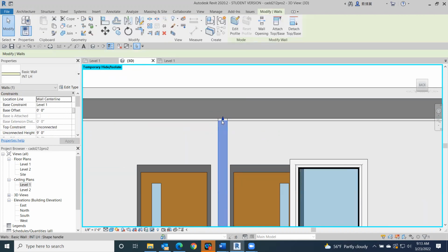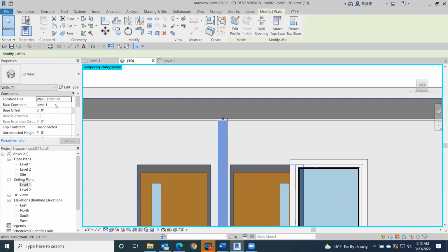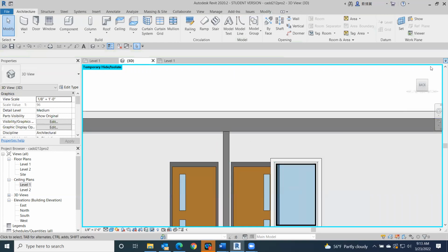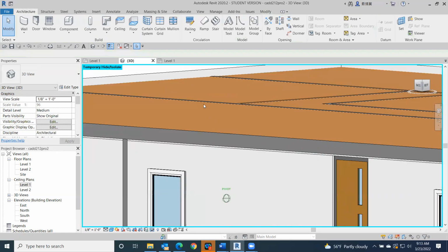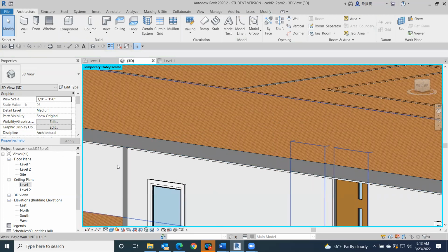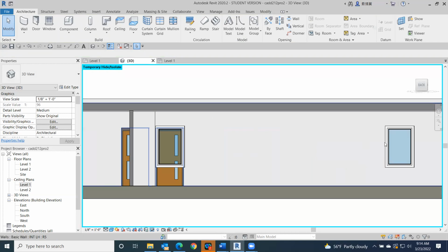And I actually have a tiny little gap right there. So let me make that 9 foot 1 inch. 9 foot 2 inches. And there we have something where the walls are actually supporting the floor above it, and it's not intersecting. So you just want to do that with all of these floors as well.